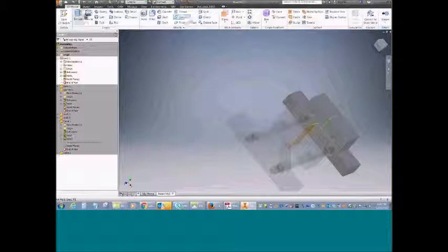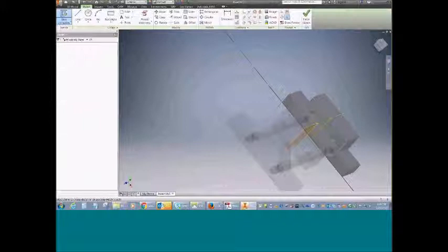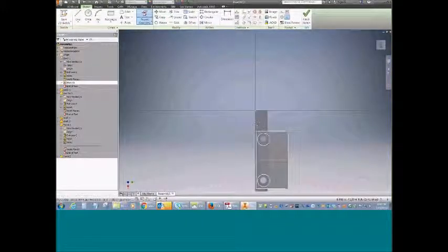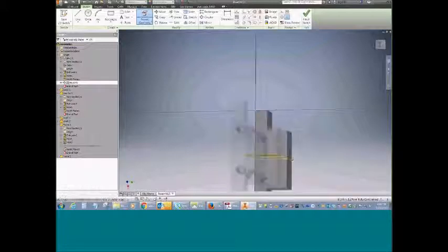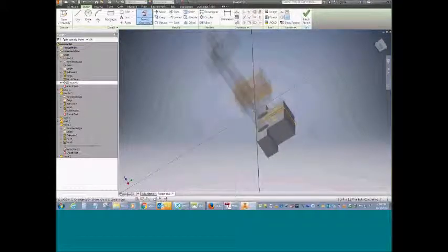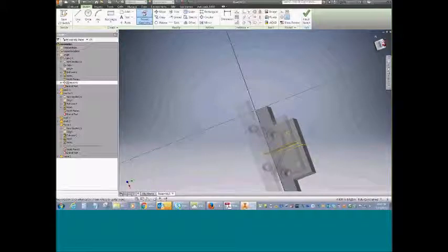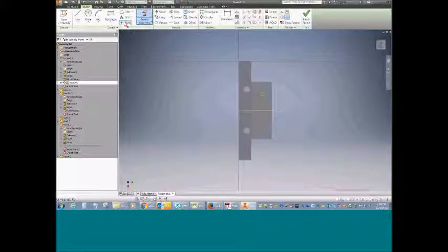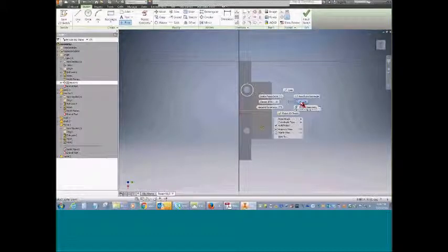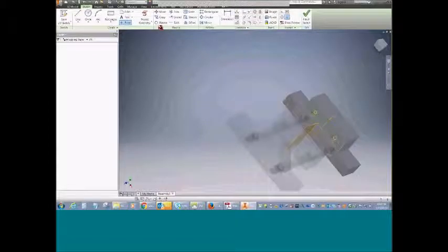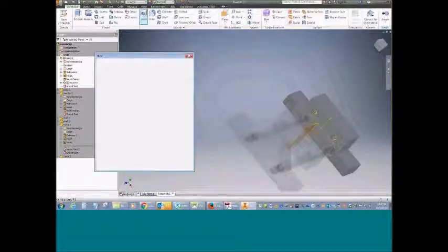And what I'm going to do is a new sketch on the front of that. And then I'm going to project the holes from my jaw plates. So I got some ghost images going there, but from those kind of ghosted jaw plates, I just projected their holes there. And then let me get back to my straight on view. And I'm going to latch some points right down on the centers of those projected holes.